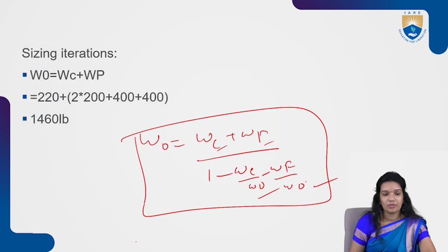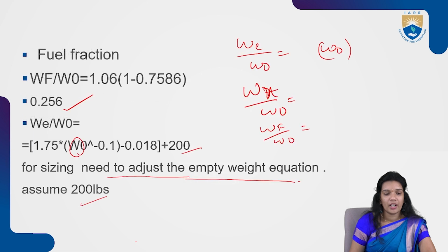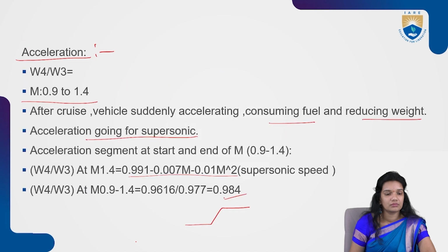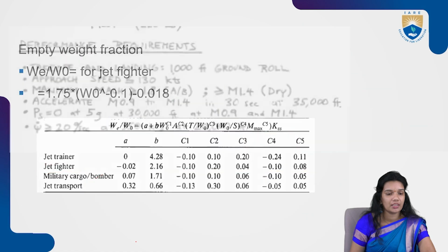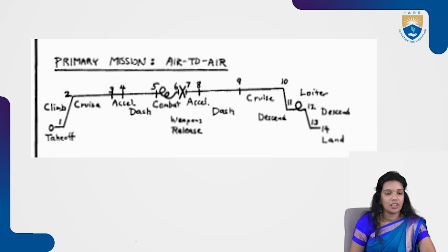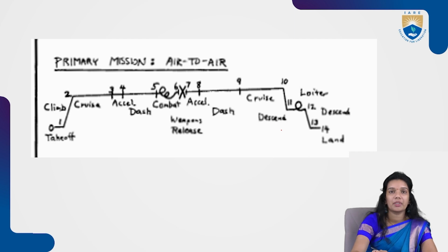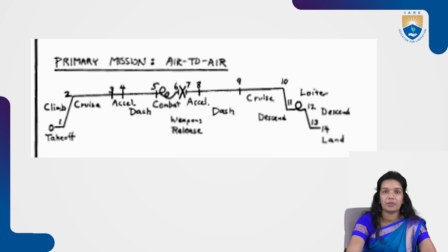So in order for me to do that, I first of all go and calculate all the segment fractions. Just to summarize things here, I'm going to calculate all mission segment fractions. At each segment, I need to calculate all of them with respect to its wing loading or Mach number or its dynamic pressure and speed. You multiply all of it, it will give you the mission segment fraction.